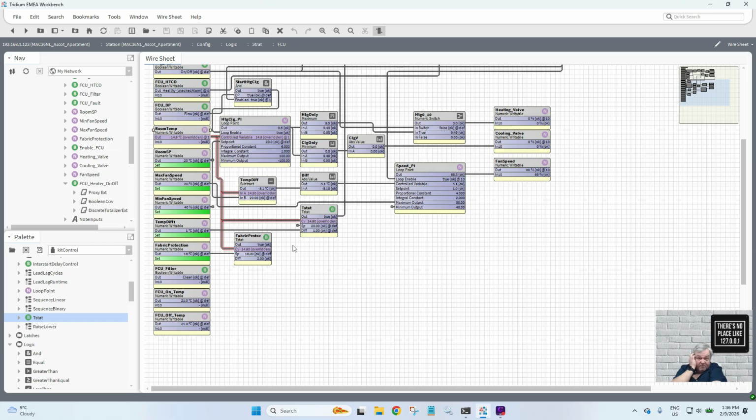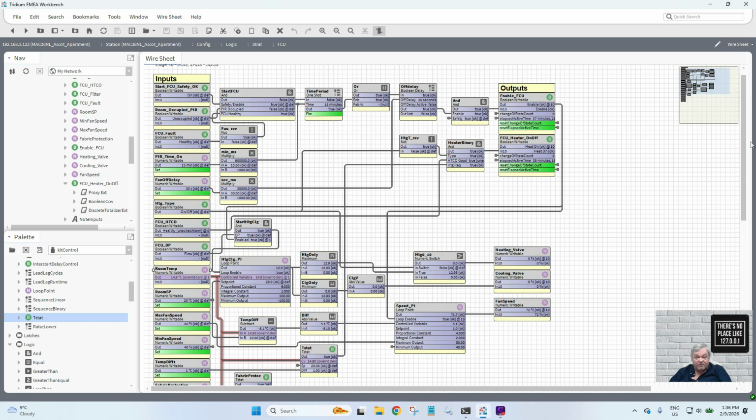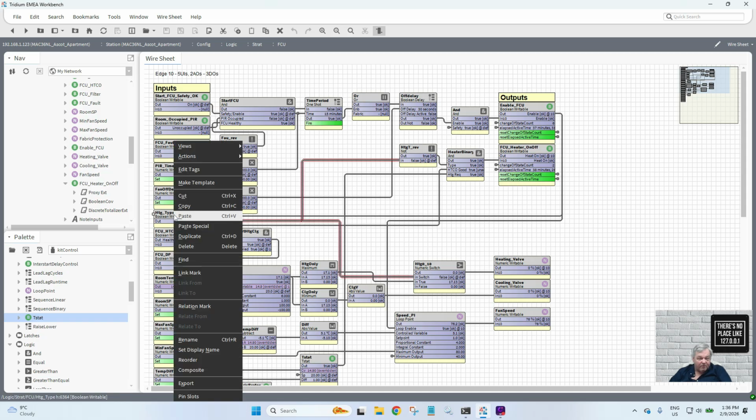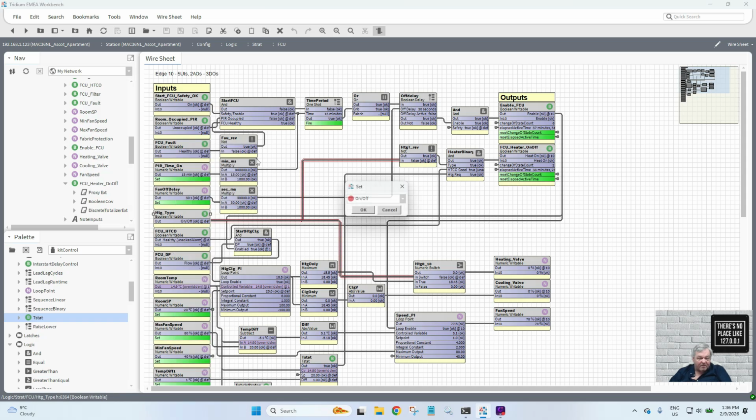And our heating valve is starting to, oh no it won't, because we have got our setting in here. We got our heat on because our setting is saying to not use the heating valve. In fact, let's just set this to use the heating valve now. Not 10 volt control, and our heating valve is on.